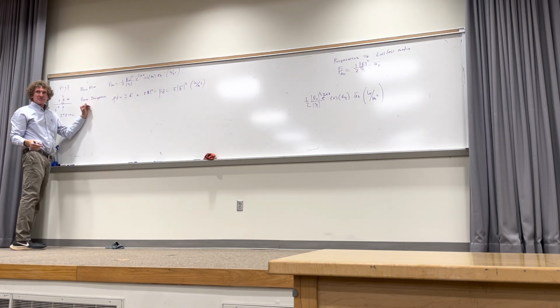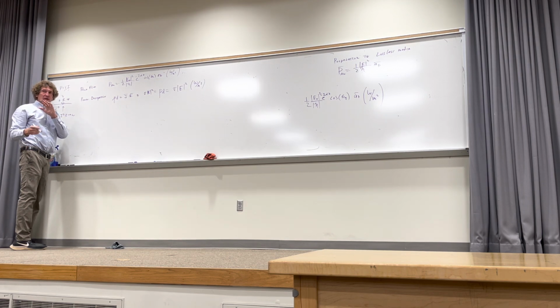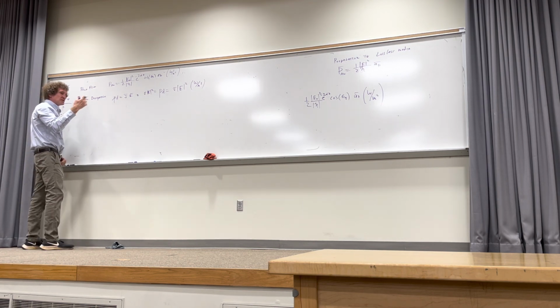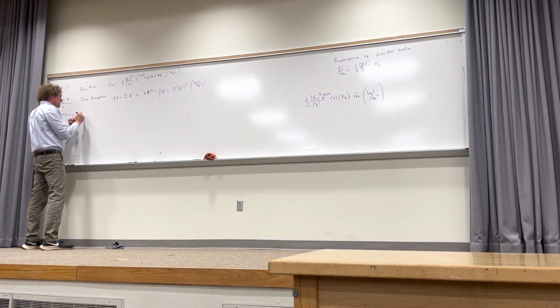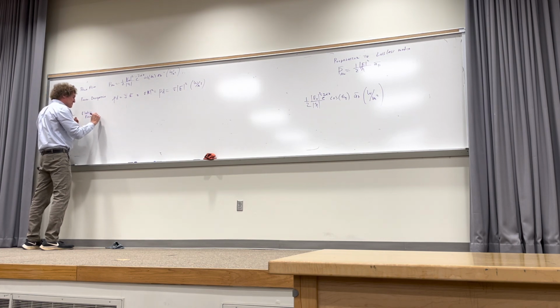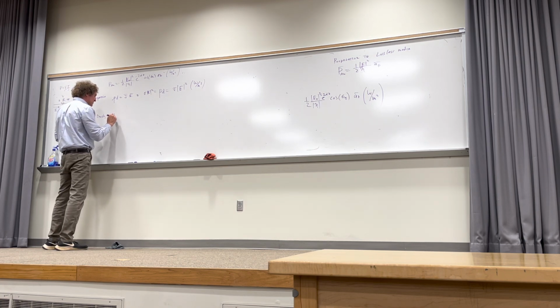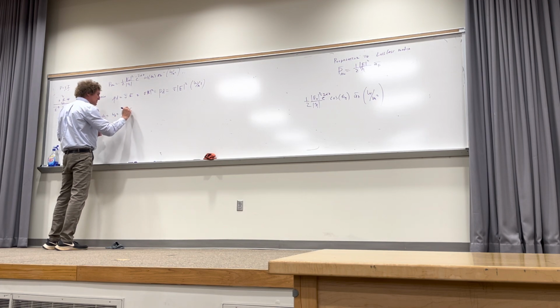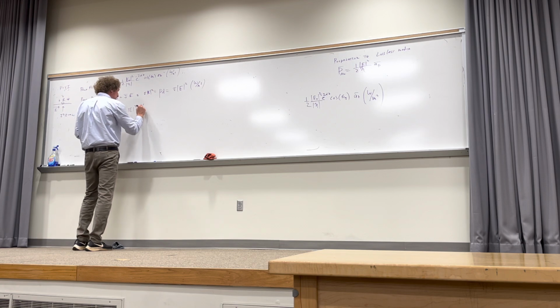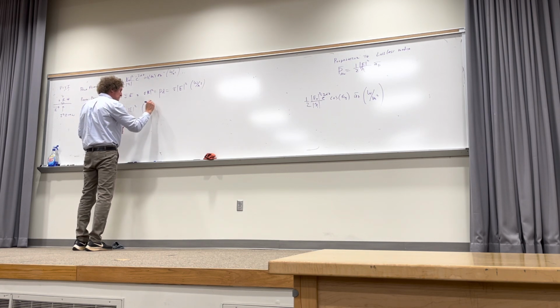That's dissipated. It's turning to heat. After you got power dissipation, now I want to talk about when you have any electrostatic field or propagating field, it doesn't matter, there's going to be an energy density. If you took a snapshot in time and just looked at the E field, you'd find what the energy density is. The electric energy density is, they use omega sub E usually, just for electric field, and it's 1/2 epsilon times the magnitude of the E field squared. And that would be in joules per meter cubed.